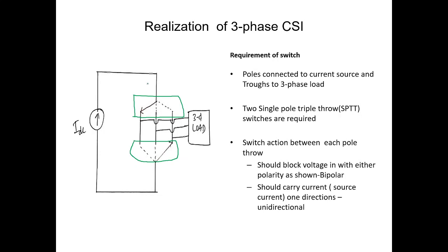By varying the switching position, you can have the current flowing through different phases. So here current through the load can be controlled by controlling the switching state. However, voltage across the load depends on the current through it as well as the load value.